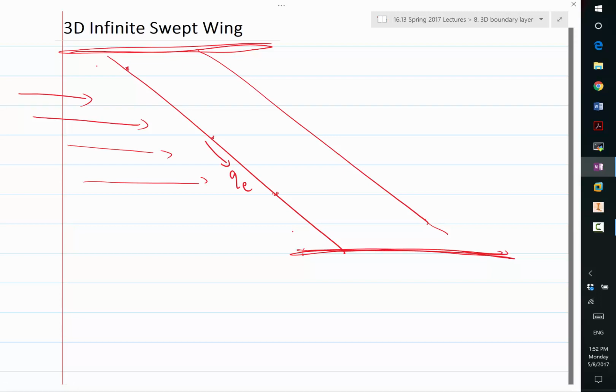Whatever boundary layer you have here is the same as the boundary layer here versus here versus anywhere. So even though the velocity goes downstream, the boundary layer shape doesn't change. And why? Because it has very strong lateral dilatation at the leading edge. Right, so if you look around the leading edge, what's the divergence of the two-dimensional velocity?